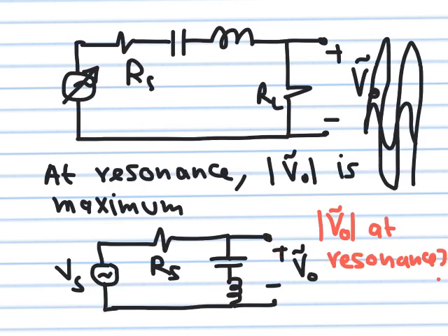What about at very high frequency? Because the impedance of an inductor is j omega L, it grows with frequency. If omega is infinite, this becomes also an open circuit. j omega L becomes j infinity. So this means that this branch is open circuit, and again V output and Vs are equal. What about at resonance? At resonance, these two really effectively represent a short circuit.